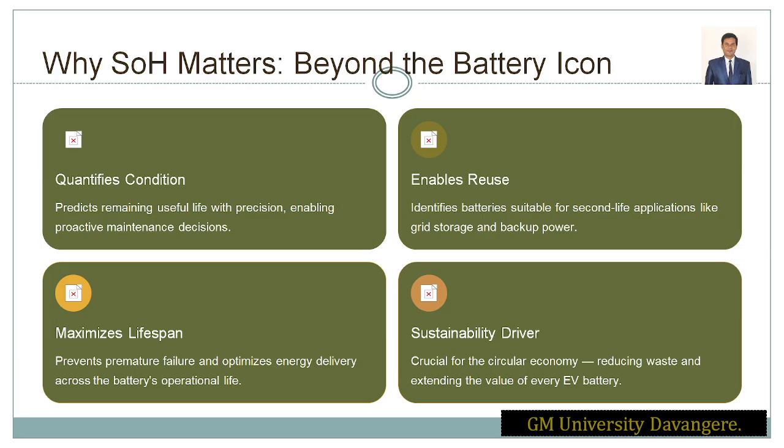So when you talk about maximizing life, we have to maximize the life of the batteries, right? So please check every time for premature failure of the batteries, and check what is happening inside. What is the SOH? How much SOH has dropped, and how much the cell SOH has dropped? Also, we have to prevent deep depth of discharge. That is what we have to observe in maximizing the life. The SOH feedback can prevent the abuse that kills the battery very early.